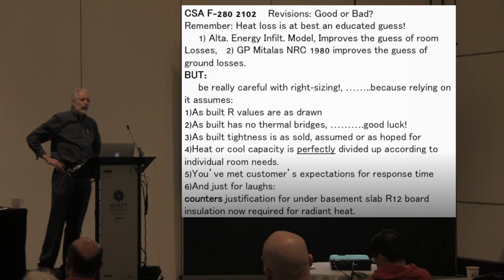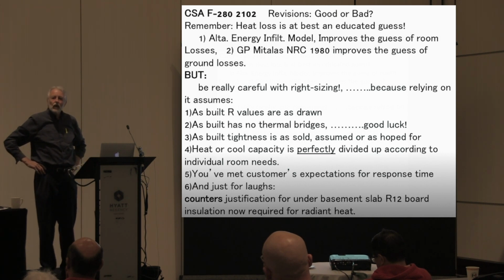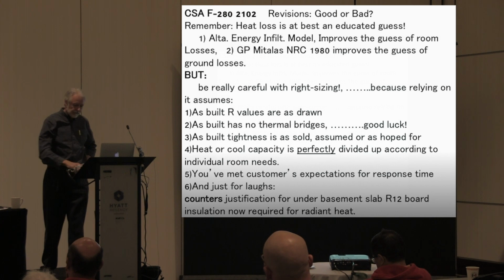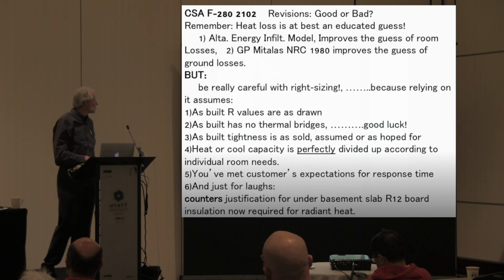The only rationale for insulation underneath is you've got really, really wet soil and water moving underneath it, sucking the heat out. So if I was building in Richmond, I'd do that. If I was building somewhere dry, it's a friggin' waste of money. But that's just a comment from myself.